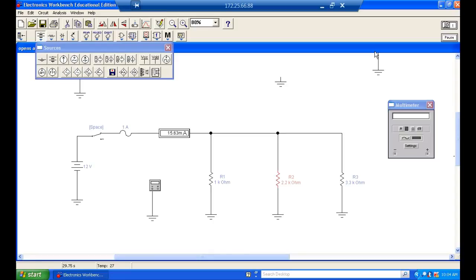But what's nice in a parallel circuit is I can do what? So in a parallel circuit, an open is not an open circuit. But what doesn't it affect? It doesn't affect the other loads. But anytime I have an open, total current always goes down. In a series circuit, it goes to 0. In a parallel circuit, it depends on the load.